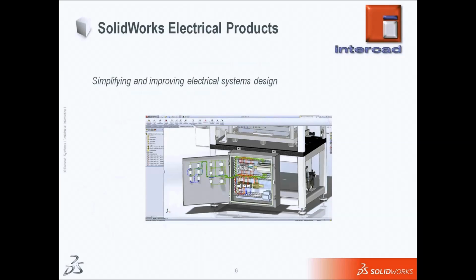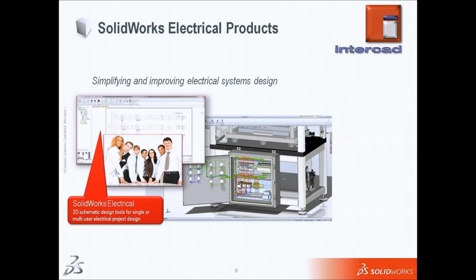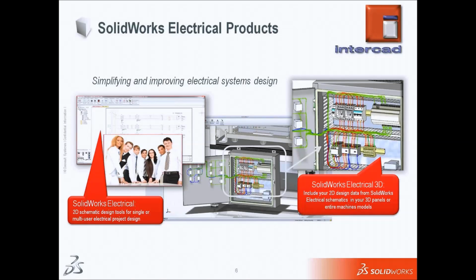The SolidWorks products, what are they? How does it work with the other SolidWorks products? SolidWorks Electrical has two products, 2D and 3D. SolidWorks Electrical 2D is a standalone software which runs outside SolidWorks. You do not require SolidWorks to run it, and it allows you to create all your 2D electrical schematic type drawings. Then you've got Electrical 3D, which runs inside SolidWorks as an add-in and allows you to do the routing of the wires and cables, and also place the electrical components in the right location, so you know that all these components fit well into the enclosure or into your assembly.